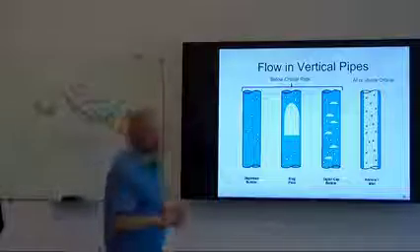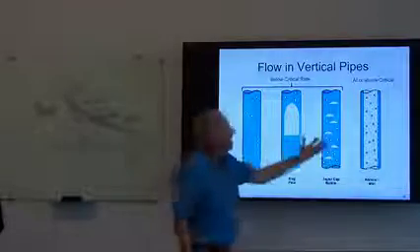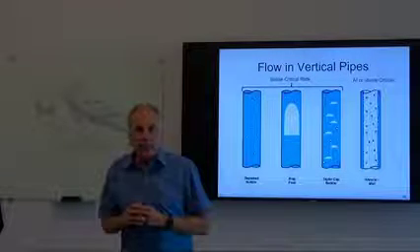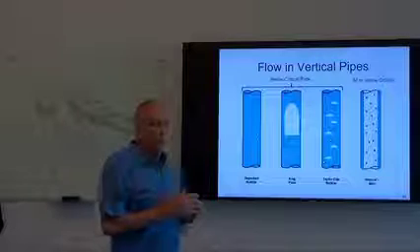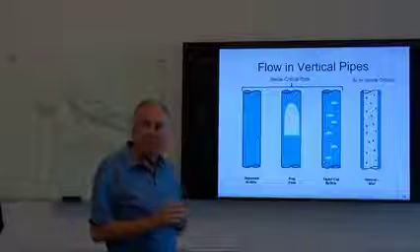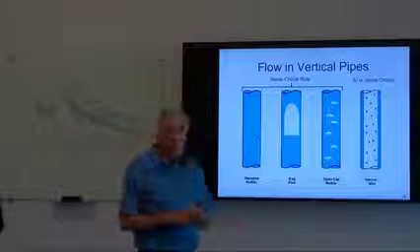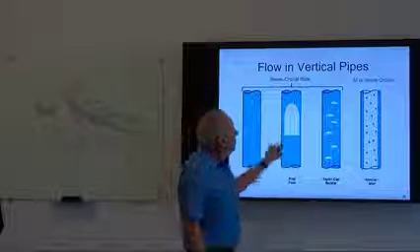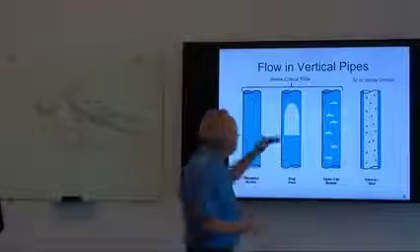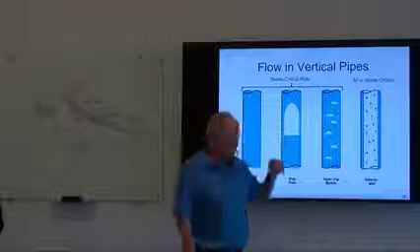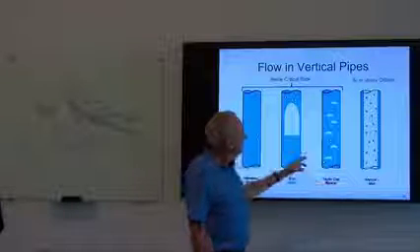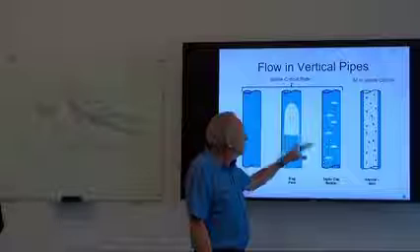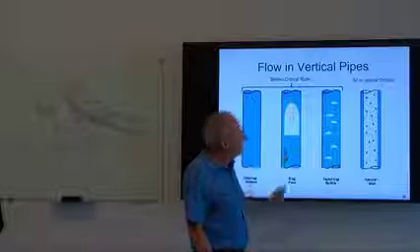All right, we can get different types of flow in vertical pipes. And here's some examples of below critical rate. One being dispersed bubble, which we touched on earlier. Often after a well is very highly loaded, we might see this situation. We might see it in very low GLR wells. Slug flow, we'll get these various big separations of slugs of gas and liquid. And sort of an in-between one that doesn't really get talked about very much is called Taylor cap bubble, but it's sort of a blend of somewhere between these two.